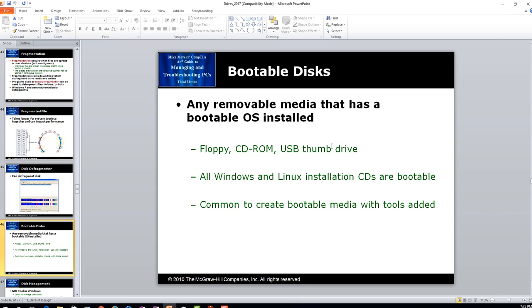That's why, on the Raspberries, if you just copied the files over to the SD card, it wouldn't boot your Raspberry. You had to use a special program to download an image of the operating system, which put the boot information in the right place.